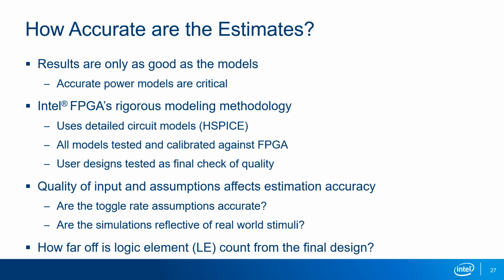So just how accurate are the tool's estimates? How confident can you be with the results in making power-related decisions, such as the design of your power supplies? Well, power estimates are only as good as the power models used to describe a device's power usage. To that end, Intel uses a rigorous modeling methodology where detailed circuit models are created using HSPICE. All models are then tested and calibrated against the actual device silicon. To further guarantee the accuracy of the models, power estimates are performed on the models using a variety of actual user designs.